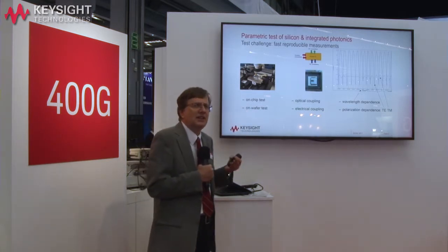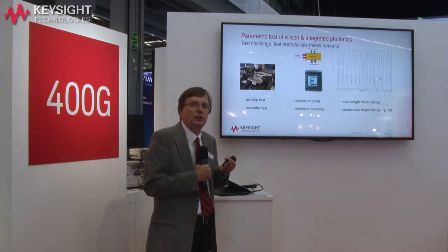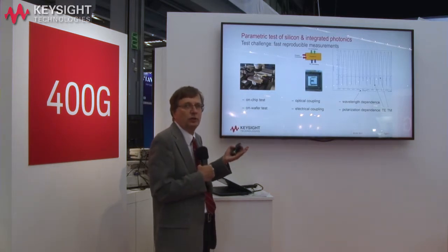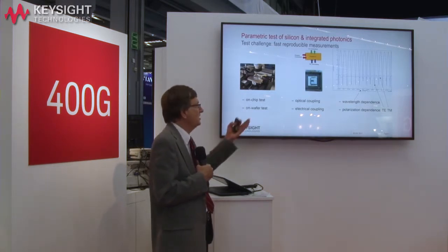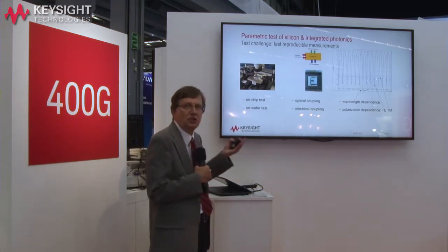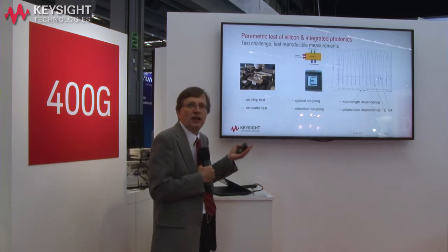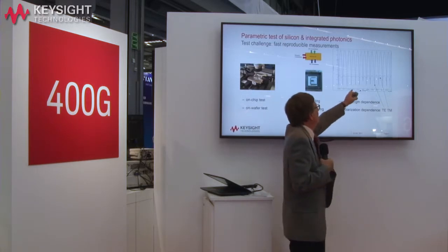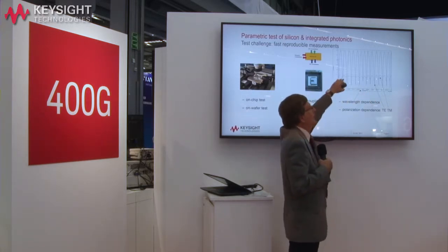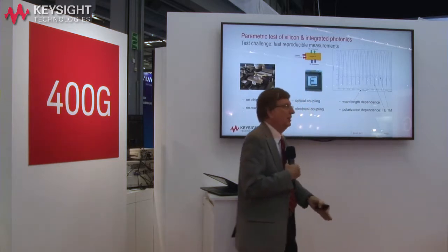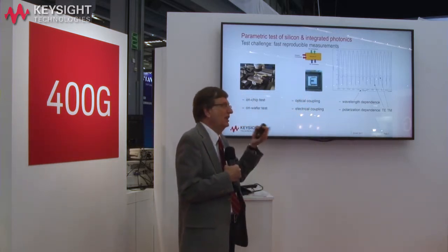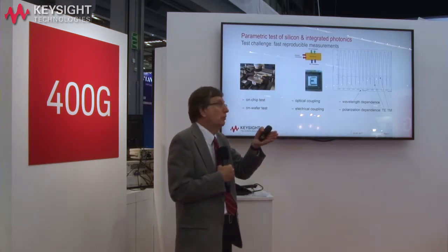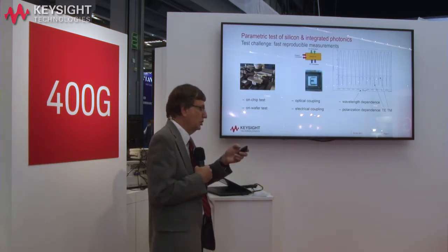And then something that comes up that's kind of unique for the optical versus the electrical is the need to do this at a chosen wavelength, or looking at the dependence on wavelength as well as the dependence on polarization. And polarization turns out to be one of the key issues. That's what I want to address today. Just looking at this, here would be a typical curve over wavelength of what the insertion loss of a device could look like in the one polarization parallel to the plane of the chip versus polarized perpendicular to the plane of the chip.